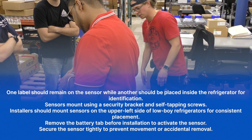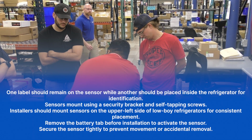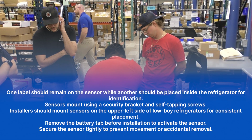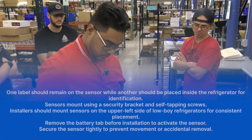Installers should mount sensors on the upper left side of lowboy refrigerators for consistent placement. Remove the battery tab before installation to activate the sensor. Secure the sensor tightly to prevent movement or accidental removal.